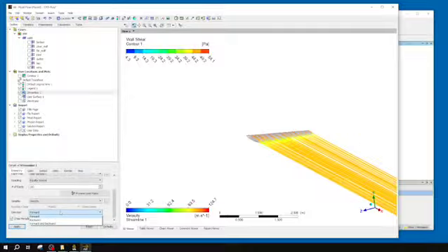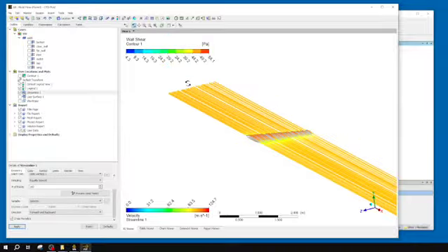But what I'm gonna change it to is forward and backwards. Gonna apply those, and now what you should see is that the streamlines start climbing forward into the flow. So we'll get nice long streamlines extending all the way from kind of their origin through the wing itself, right?